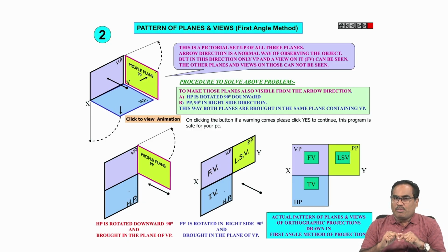When you come to third angle projection, it will change. I'll show you when I get to it. Right, so you have to remember and draw exactly like this: the front view, below that the top view, and the left hand side view and right hand side view.